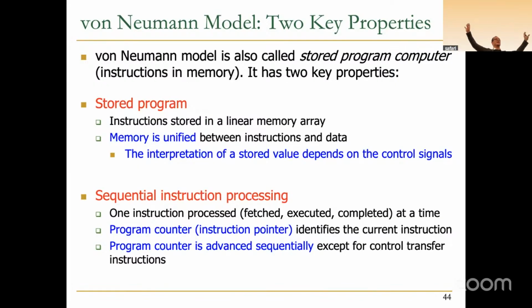How big of an array do you need? All of them are larger, and based on the timing and verification lectures, that requires a huge amount of combinational logic. The delay is much larger, right? If you have only 8 registers, your decoder is much smaller, your multiplexer is much smaller, your array is much smaller, so your access times are much faster. Okay, very good question, because there's no magic. Basically, we built up to all of these, right?